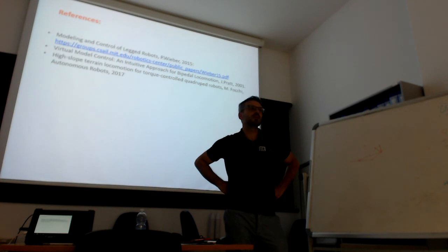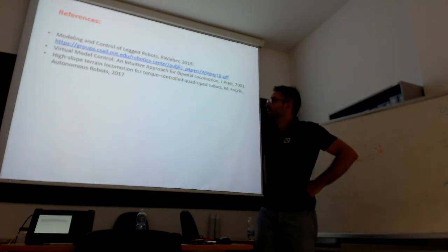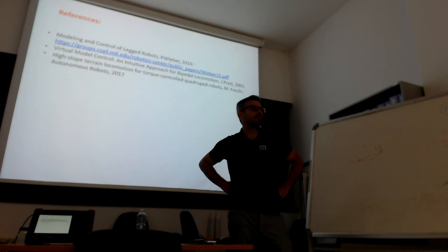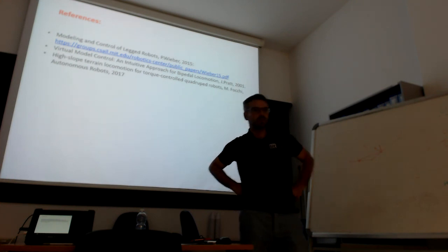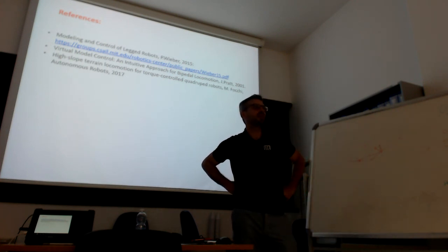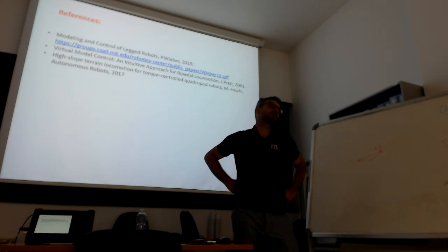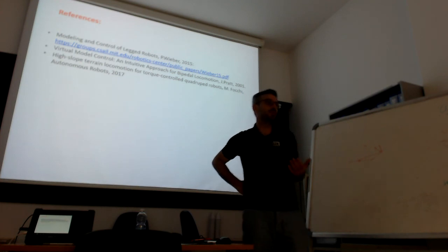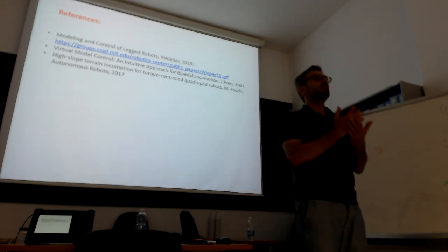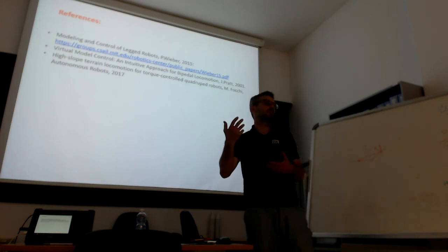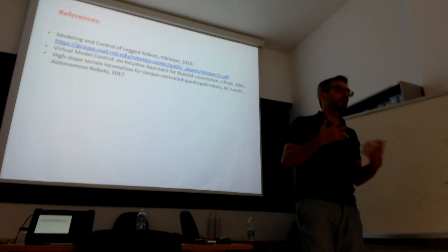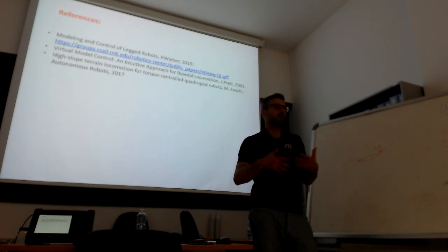When we use optimization, this is a regularization, so it doesn't mean that it will stay in the middle of the friction cone. You try to stay as much as possible inside the friction cone, but if your motion requires very high tangential forces, it will allow you to find this tangential force. Whenever you can, you choose a more robust one. But the nice thing of optimization is that it allows you to get to the boundary. Why? Because these are in the cost function and they are not hard constraints. So normally they have a low weight.